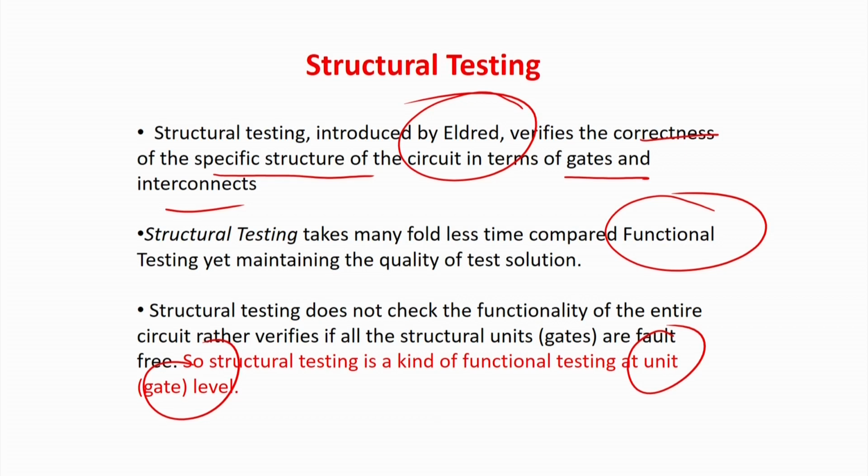So optimization is not in the performance of the circuit. You can take this as a thumb rule, not a very regular rule, but mostly a thumb rule. When you are talking about optimization, it is mainly at the CAD part, the algorithms to design the circuit or test it, so that even if it is a very big system, I can do my job very quickly. There will be very minimal quality compromise in the device or the circuit. When going from functional testing to structural testing, I am not testing the functionality, and I am also not very explicitly or rigorously testing the interface.